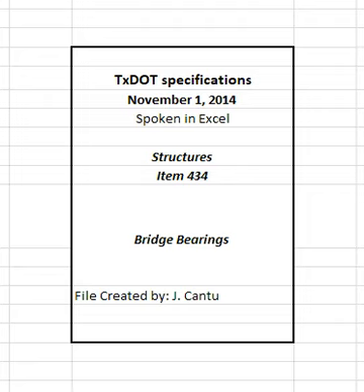2. Materials. 2.1 Plain and laminated elastomeric bearings. Furnish bearings produced by a manufacturer from elastomer formulations approved by the department. The department's MPL has a list of approved bridge bearing elastomer formulations. 2.1.1 Elastomer. Provide elastomer for bearings formulated from previously unvulcanized 100% virgin polychloroprene rubber polymers meeting the physical properties, heat